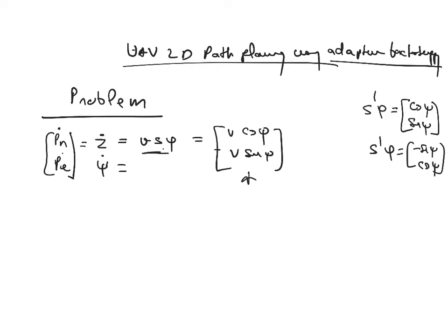You might remember the simpler guidance models where we are using first order, second order autopilot. So it has alpha psi, that's the gain of the autopilot. It's a proportional controller, and it's psi commanded minus psi. So that's the autopilot, right? Simple. So the input is psi commanded. You give a psi commanded, and it takes some time and converges to that value. And similarly, we have v dot, so it is alpha v times v commanded minus v.